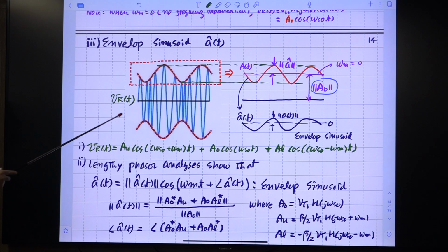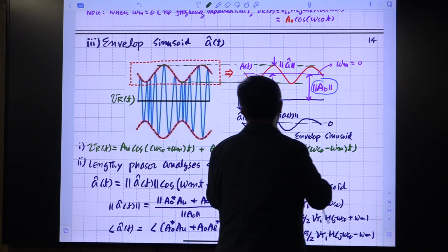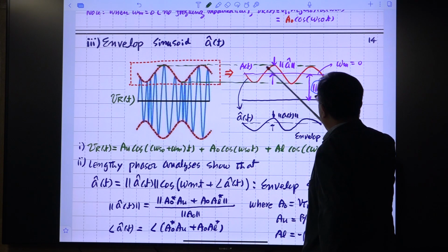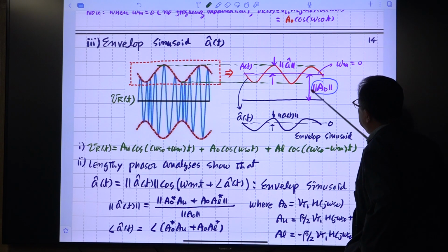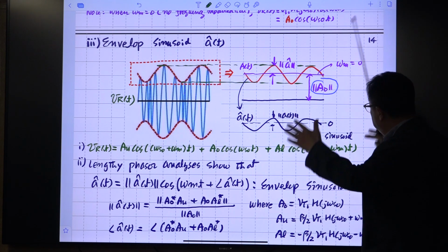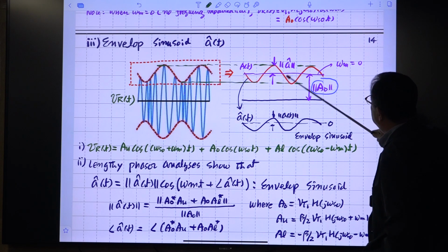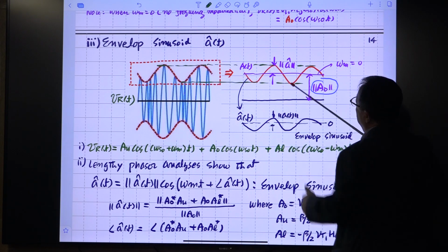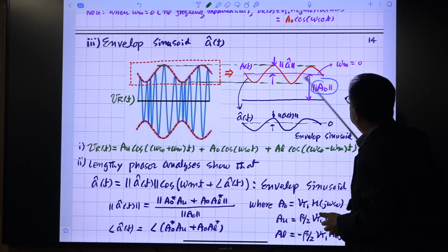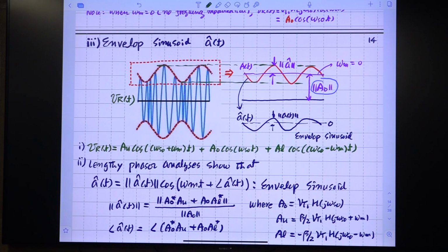It is a combination of AM and FM signal. So which one is this? This envelope is expressed like this, and the envelope itself is denoted as A(t), large A(t). And this is the DC bias, A naught, this magnitude, right? And this is the magnitude of this sinusoidal component. So we just take this part here, or we subtract this one from A(t). Then we have this. It's the same thing. Conceptually, graphically, just take the AC part, or numerically, just perform this operation.